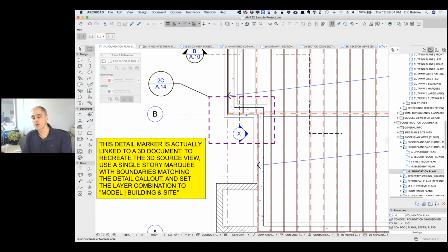So great point. Can I use model files in a solo license? Okay, so Monica, you have ArchiCAD Solo, which means you can't reference in external files yourself, but MasterTemplate's Hotlink Module file will work within your Solo project. You won't be able to update the module file directly because of the limitations of the Solo project, but you can use what's in there. And you can delete it if you don't want it, but you can't actually rework it and put it in again with a Solo.